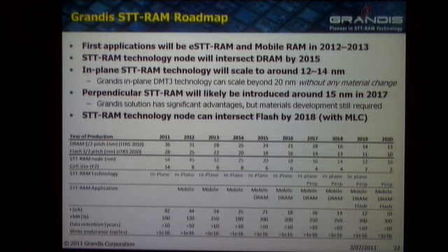Finally, this is the last slide. This is where I see the technology evolving. This is our roadmap compared with, as reference here, the DRAM and the flash roadmaps. Right here today, we're working at 54 nanometers, 14F squared with Hynix. The next design, we might actually skip down to a 30 nanometer design at 8F squared. And there I think these mobile applications become interesting.